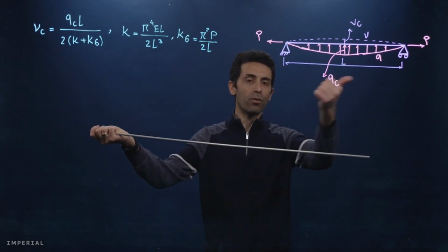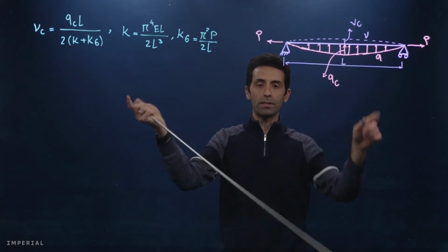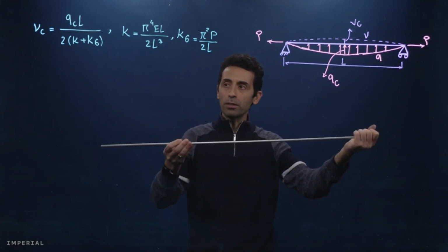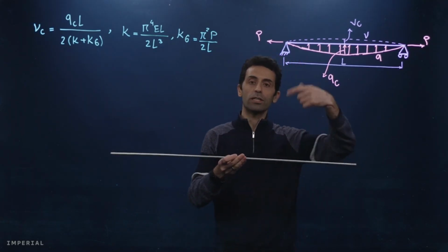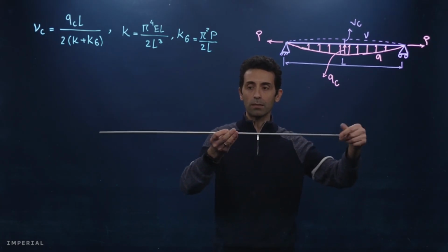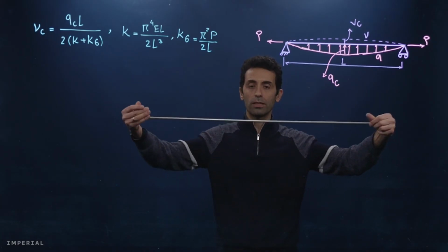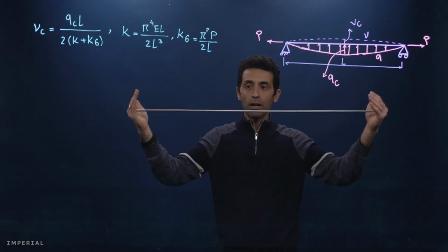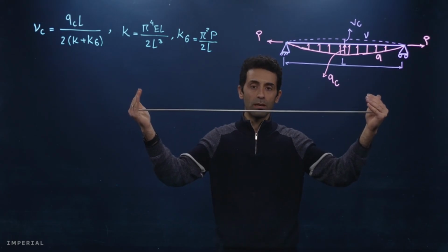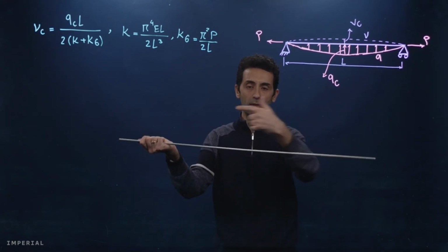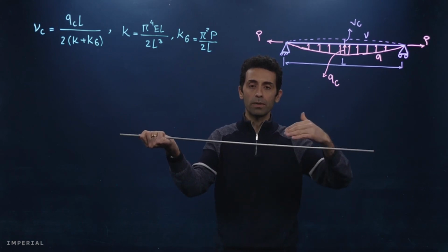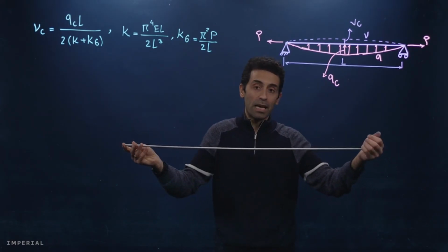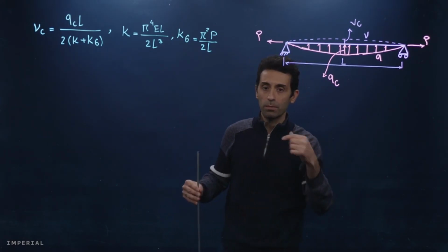And when this force is pointing in opposite directions, this beam is under tension, correct? But what happens if we change the direction of the force? What I mean is that when these forces are pointing towards each other, then our structure is under compression, right? And if I apply this force up to a certain point, we may see that this axial force is now driving the structure into bending, correct? And this bending can be abrupt. Let's look at this problem mathematically.